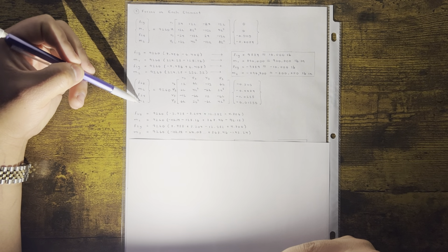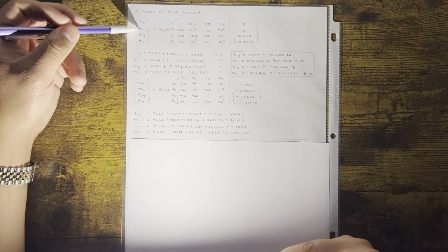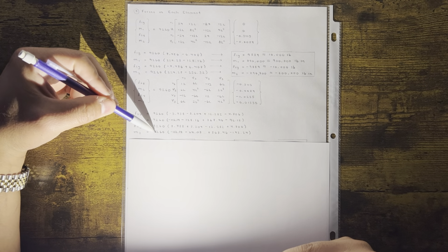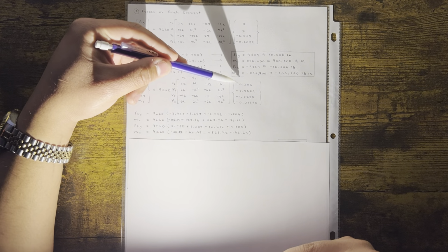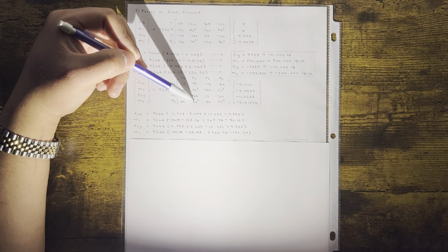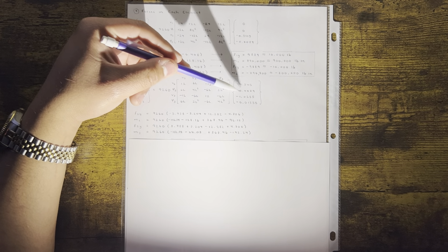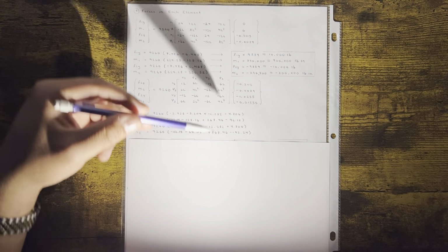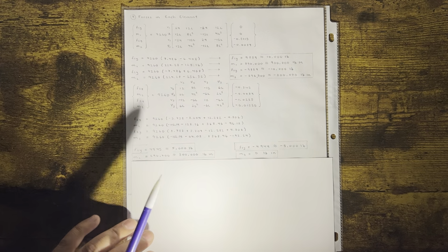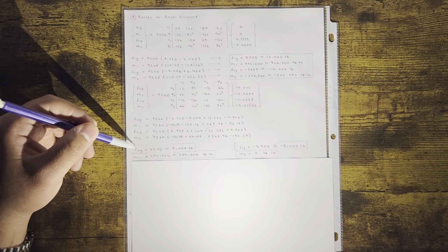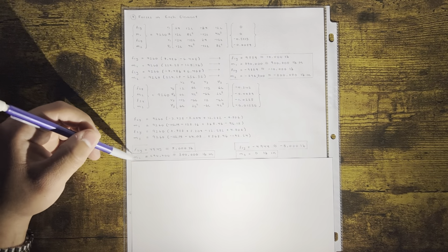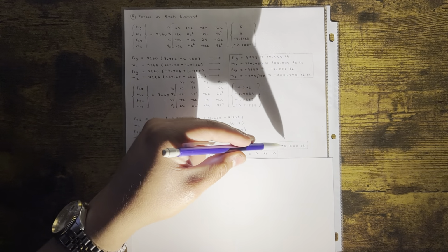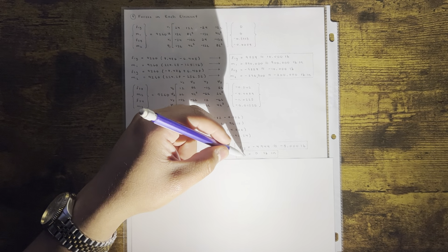We'll do another one. Let's do M3 now. We did M2 and M1 up here, so let's do just another random one. M3 is equal to 9260 times 6L times V2, 2L squared times Phi2, minus 6L times V3, plus 4L squared times Phi3. Once you solve for those numbers, F2Y is about 5,000 pounds. M2 is equal to 300,000 pound inches. F3Y is equal to minus 5,000 pounds. And M3 is equal to 0.